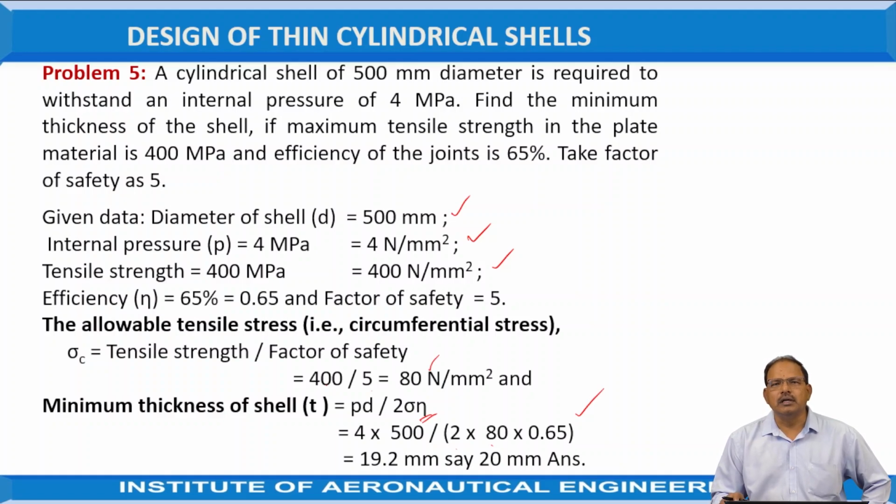So, what is the pressure allowed in the cylinder, particularly for thin cylinders? Based on that, we calculated the pressure as well as the stresses induced. And sometimes, since the joint is made by welding or other means, the efficiency of the joint is considered when we determine how much pressure is allowed. The third one is the safety factor, which we have taken now. So by using this information we can design the thickness of the shell that is required for the given pressure of the fluid that is allowed.